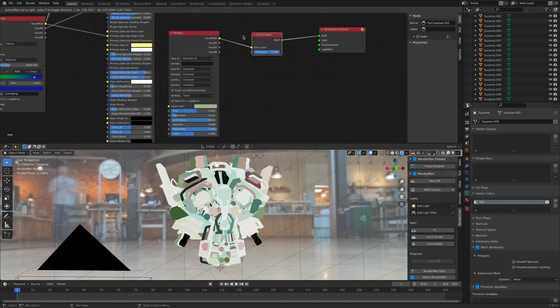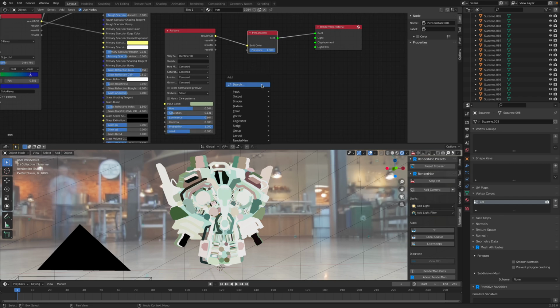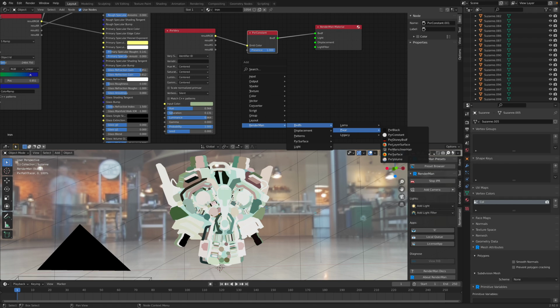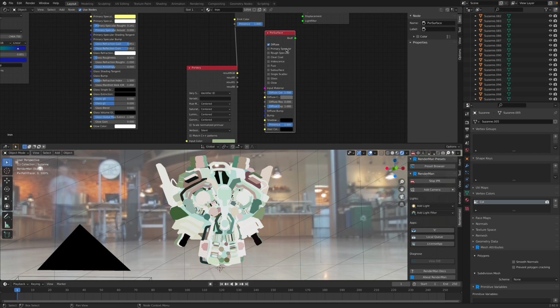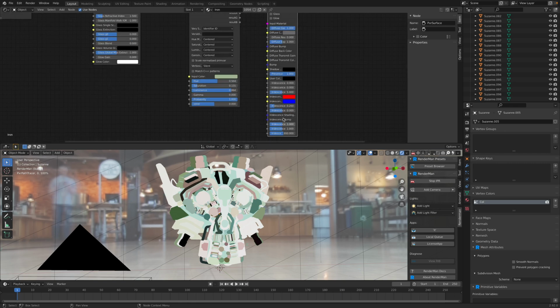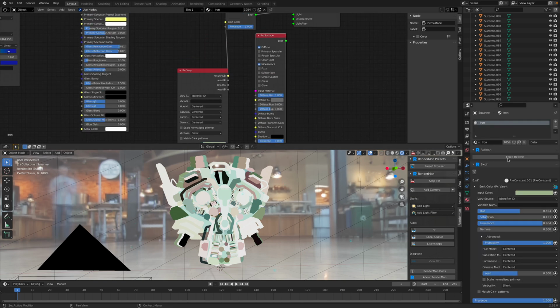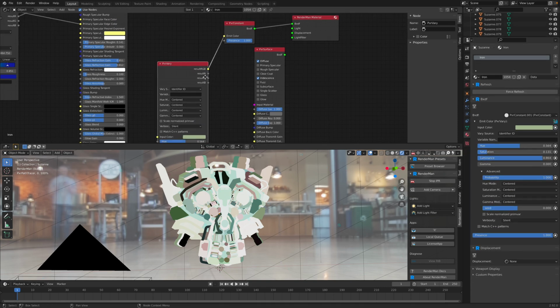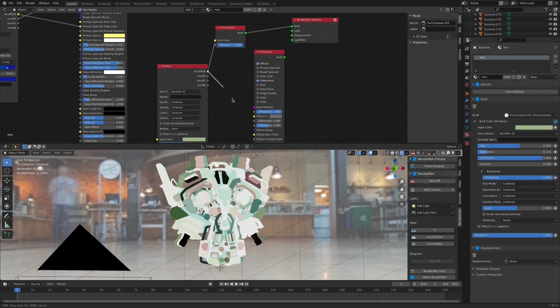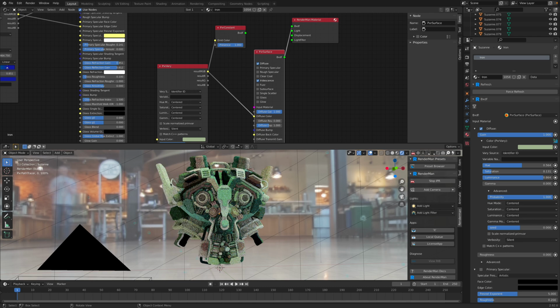And then instead of using Pixar constant, we can use the Pixar material. Oh, okay, RenderMan shader is here. So Pixar surface shader. By default, only diffuse is being turned on. If I turn on things like iridescence, iridescence will show up there, but it's easier to control it over here. So plug this into the diffuse, for example, and this goes in the XDF. So different color per objects.